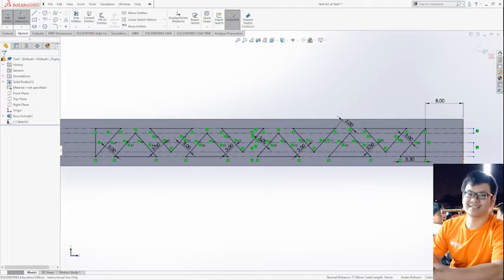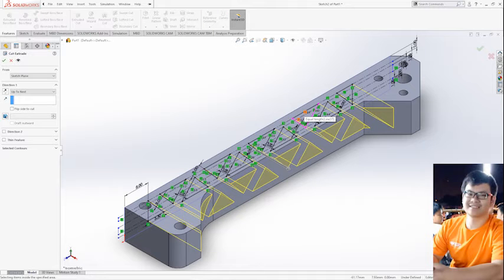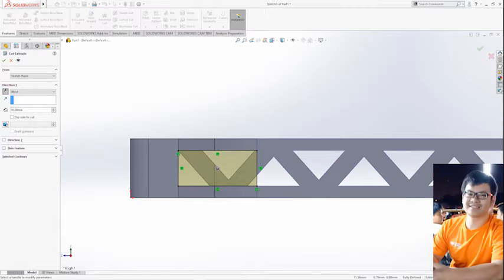Draw 8 isosceles triangles using the line created in Step 10 and set the sides of the triangles parallel to each other with dimension 3 mm. Draw a triangle that's the same as the triangle on the right side. Step 12. Using the extrude cut feature, choose up to next for the cup shape from Step 11. Step 13. Draw a rectangle and use corner rectangle to extrude cut it. Make the surface flat.